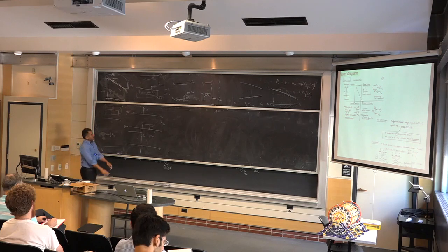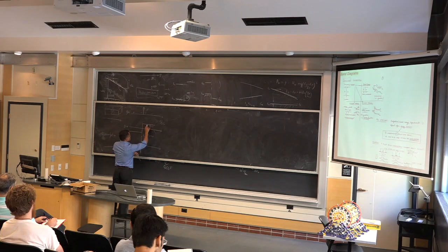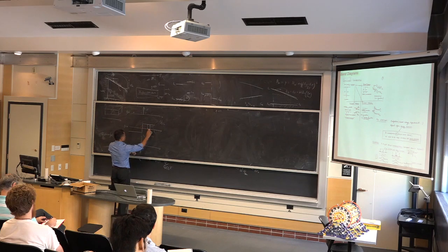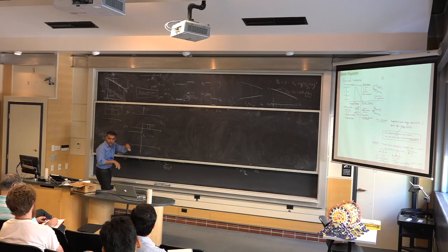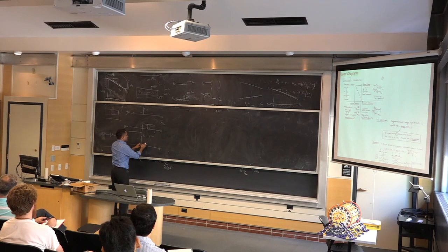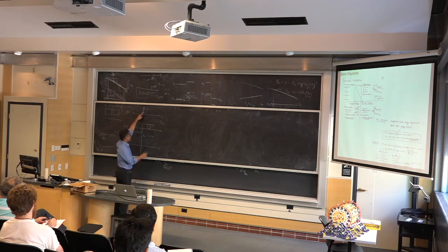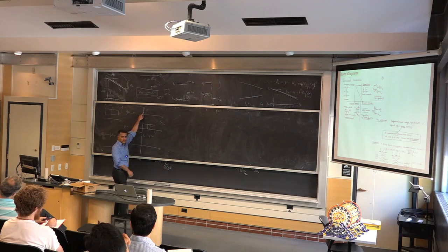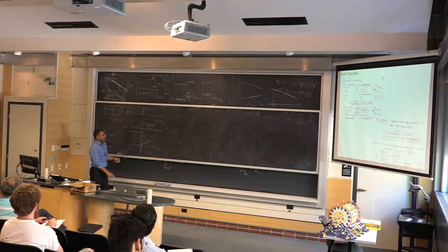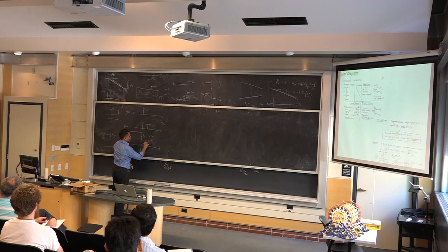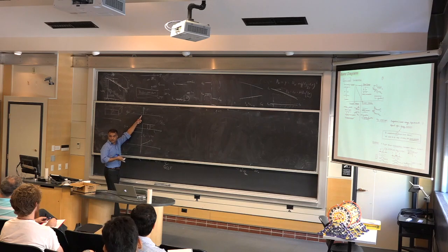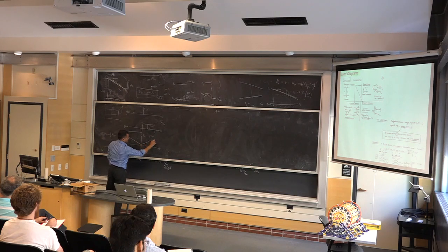Because there's a constant positive field here, when I integrate that, there'll be a linear change in the potential. So the band will change linearly, not parabolically or power law. It's linear. And sometimes you get confused: what direction is it going, up or down? Here, you should just look at the charge. It's a positive charge. The conduction band is going to bend so that the electrons pile up around there. That's because if I release an electron in the conduction band, it should go towards the positive charge. So it's coming here. And similarly, if I release on the right side, it's going to come this way, and that's my conduction band as a function of x.